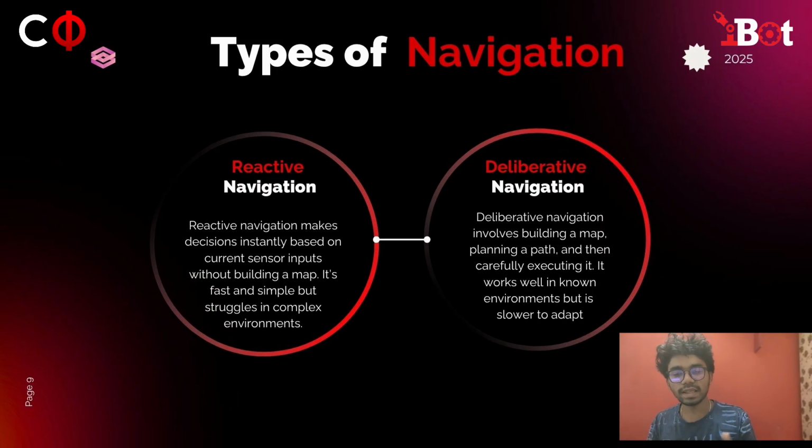And then in deliberative navigation, it's more of path planning on how to get from here to here. These are all the possible combinations I can go with, so I would choose the best optimal one. But this might not be good enough because of the processing power, and for sudden changes, like what if, while solving a maze or cleaning the room, a cat appears in the room. For sudden changes, we need some reactive navigation, and for optimized paths, we need deliberative navigation.